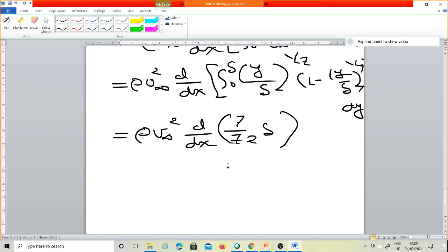For the Blasius form, what we wrote last time is that tau naught is equal to mu du by dy, right, at y is equal to 0. Then we equate these two equations, if you remember. That is okay when the relationship is linear or parabolic. But when you have the turbulent flow, that is, if you see the relationship is 1/7, it means u by u infinity is equal to y by delta to the power 1/7. You must use another form, that is the Blasius form, but this one is for turbulent flow. So you need to note down this equation. Please note it down.